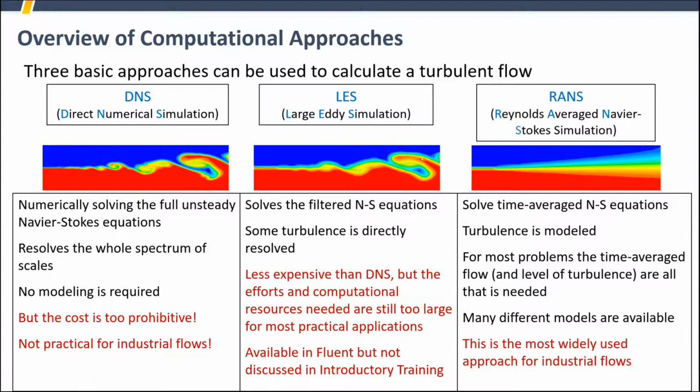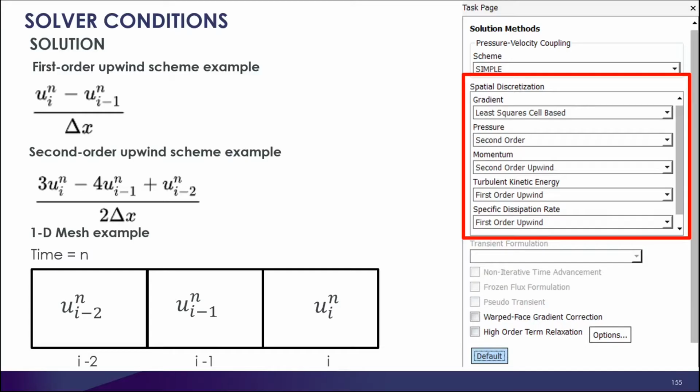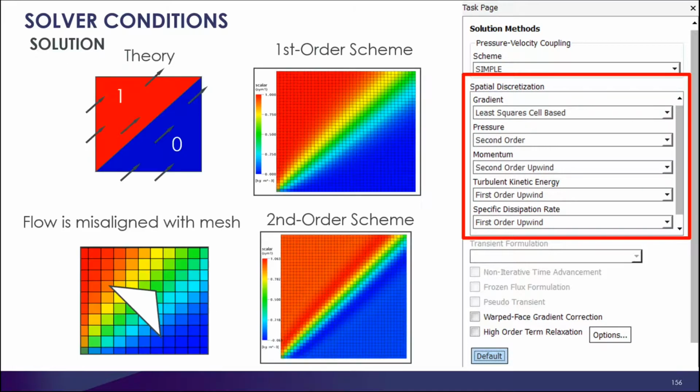So in Fluent, generally it's more of a commercial solver. You're basically using first or second order. Generally, you leave it all second order. I think first order is okay for turbulent quantities. So we don't have the higher order spatial discretization schemes, but as we went through before, direct numerical simulation is helpful for not really anything outside of really high level academic studies.